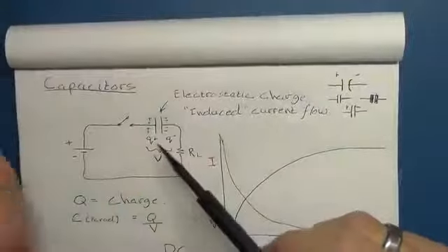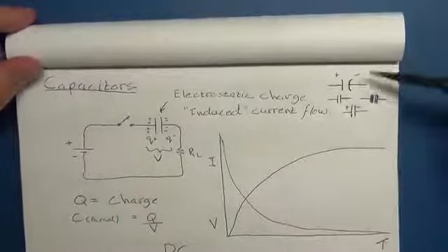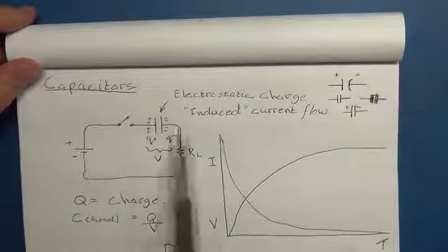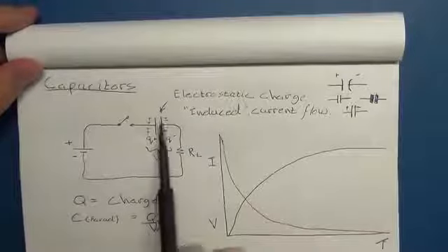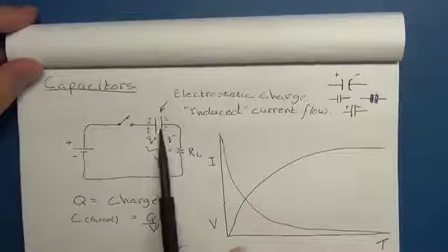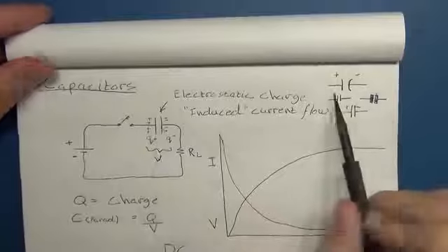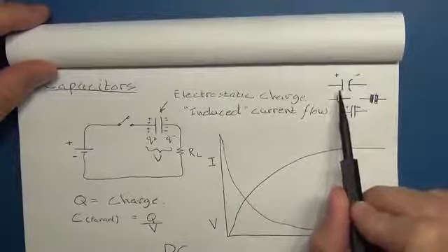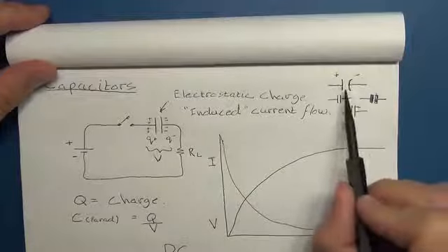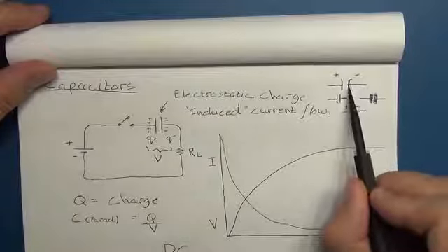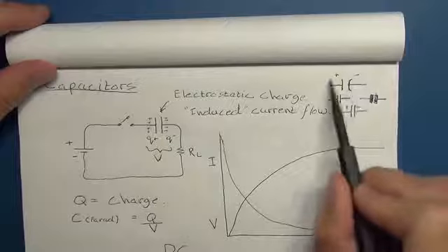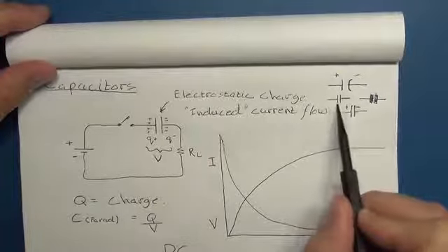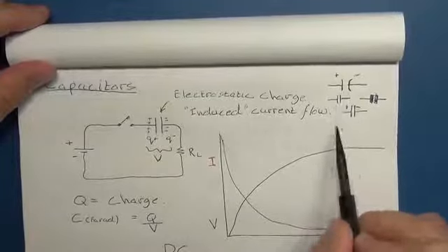Right, so the first thing to have a look at and understand is that the electronic or electrical symbol for a capacitor is this line with what seem to be two plates, which is a nice representation because that's exactly what it is. Now you may find an electrolytic capacitor, which has got polarity and has to be connected up in a certain way. It's got this more rounded side, denoted as the negative side, and the straight plate as the positive. Or just simply a normal capacitor with these two plates.